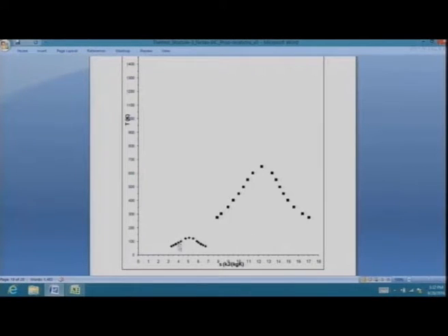So here is what you see. This is nitrogen, the TS diagram of nitrogen. This is the TS diagram for water. And what happens now is that let's take the case of an inlet of a gas turbine. I've been mentioning that temperatures there like 1400 Kelvin, 1600 Kelvin are now typical in aircraft engines and also land-based power generating units. If that 1400 Kelvin is over here, then for nitrogen, we are way, way far away from this saturation dome. In fact, even if you look at water at that state, we are still far away from this thing.